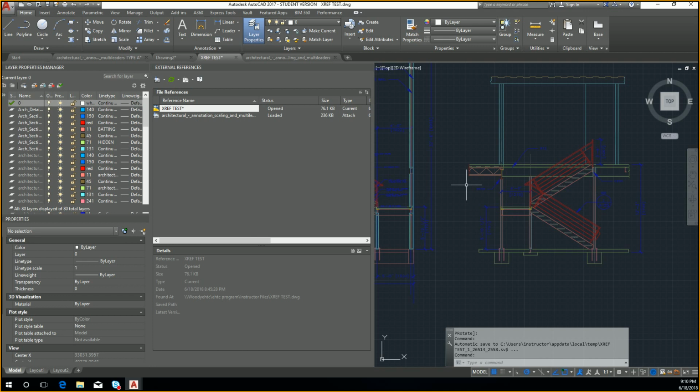Yeah. And for the shortcut, you go Control S, instead of always finding the save button. Try to remember the keyboard shortcuts, it will save you a lot of time. And then now type I. If you just insert it right now, just so you can see the difference, say OK. Insert it somewhere. Notice how nothing's changed, because it's drawing from its snapshot memory. Once you've inserted a block, it keeps living as that one block. So you can insert this 100 times, nothing will change.